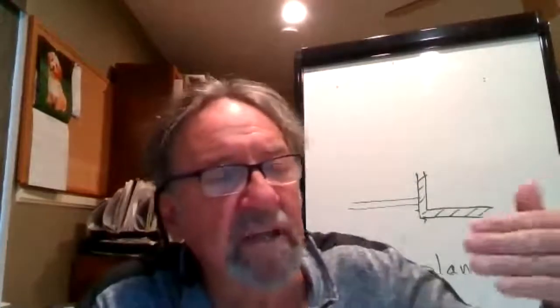And if you know the length of the room, that stuff can waste pretty easily because you can end up with a bunch of little stuff that you didn't anticipate. So, the room is 21 feet 2 inches, so it's kind of an awkward length. You don't want to have just two pieces, right? Because then they'd all be joined in the middle. So you want to have at least three pieces.